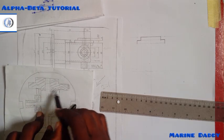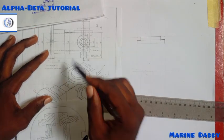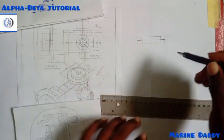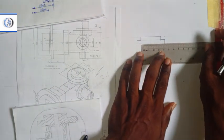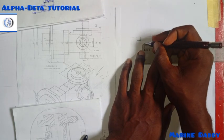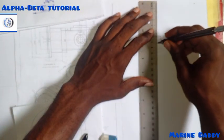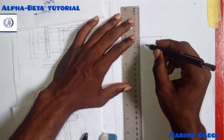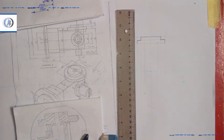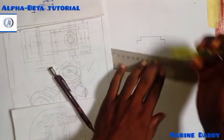Now the length at this part, that's the length from here to here. To get the length from here to here, I can come over to this side. I cannot see the length here because this is the front view, but from the top part I can see the length. So I can see that here to here is 13. So from the center, 13 times 2, 26. So 13 to the right, 13 to the left, 26. Understand? Okay. After doing that, I can outline.